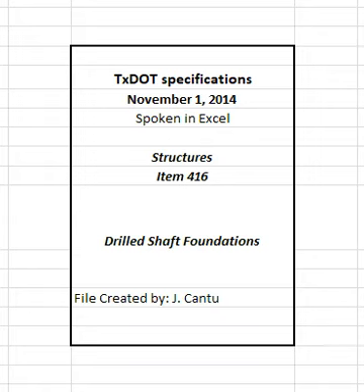Extend the cage as directed for bridge shafts with plan lengths at least 25 feet that are lengthened more than 33% of plan length. If the cage does not reach the bottom of the shaft, it may be suspended, or a portion of the longitudinal steel may be extended to support the cage on the bottom of the shaft. Bars used to extend or support the cage may be lap spliced or welded by a qualified welder. Place the extension at the bottom of the shaft.